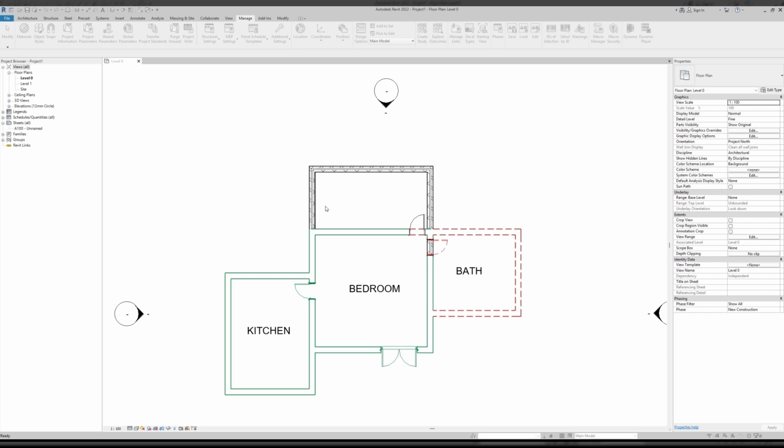So the same way, in demolish plus new, you are not showing existing, but you are showing new and demolish, and temporary works. In new, you are not showing anything other than new. In previous plus demo, this is actually showing the previous phase, the existing phase, where you have existing and your demolished existing elements also.